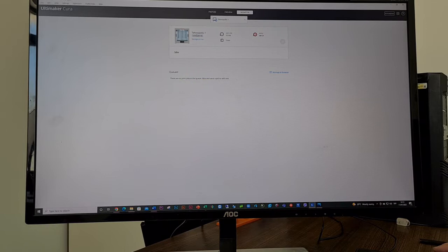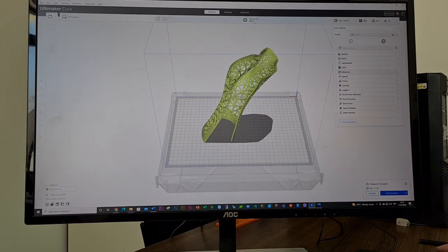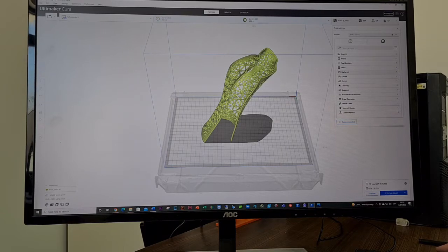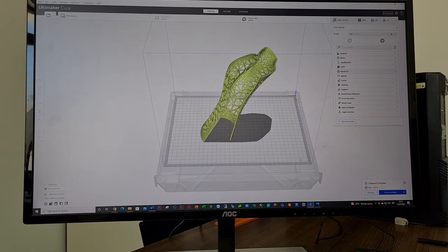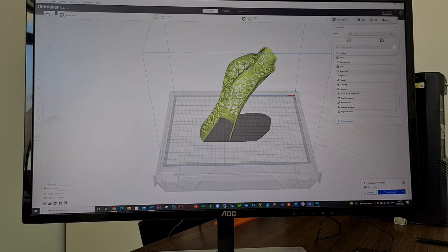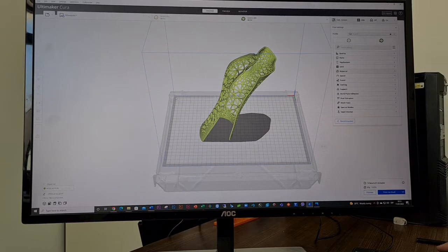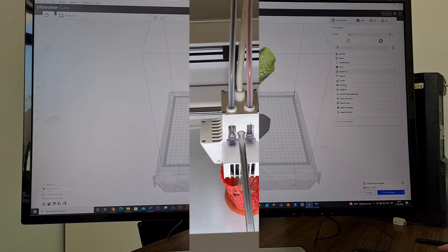We can set printer to work from our home, but we have to keep in mind that the material which is chosen on our software is the same as material placed in 3D printer, and there is nothing on the printing board, and also the printing area of our 3D printer is prepared and clean as it should be before every printing project.